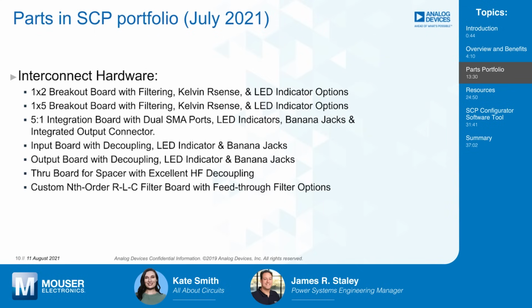Right. There's no way you can have a custom board without at least a few inches of PCB trace. So we have found that you actually get some filtering for free. For example, on the through board, it actually tends to mitigate some of the high frequency response in terms of how it rolls off. And that does a good job kind of approximating what at least a few inches of PCB trace will do. So in some sense, those parasitics actually work with you instead of against you.